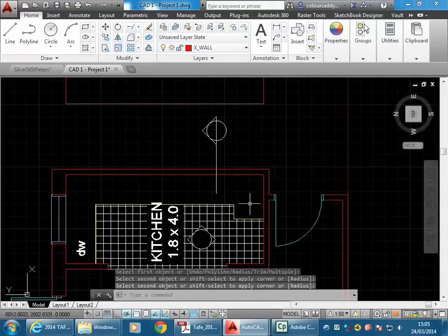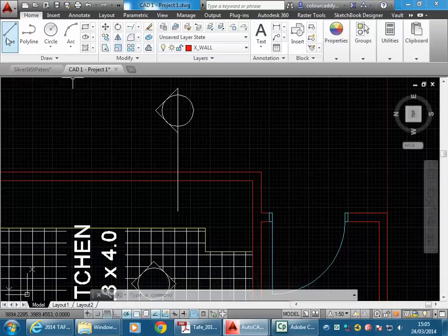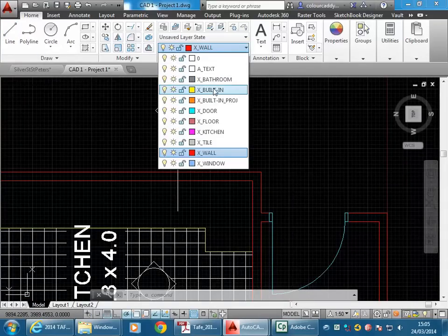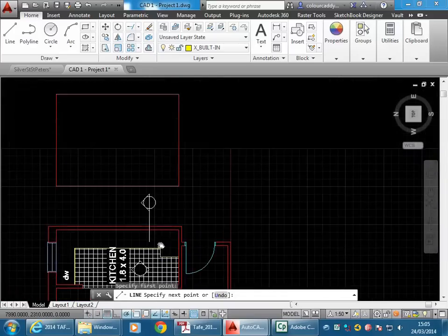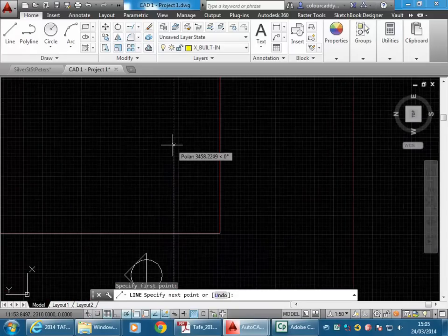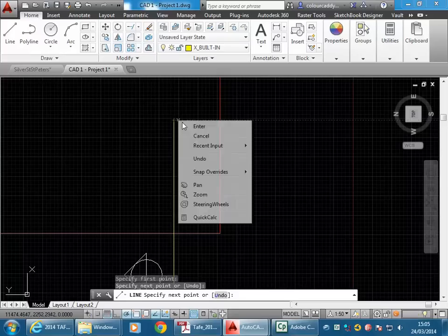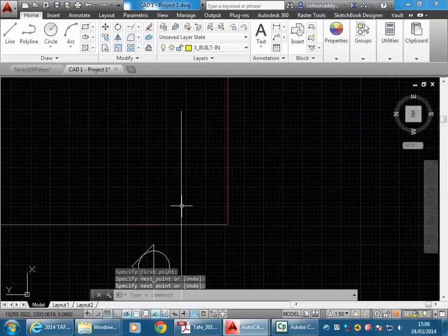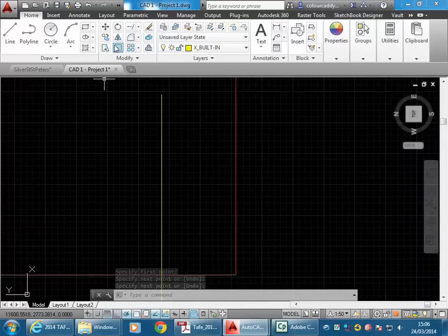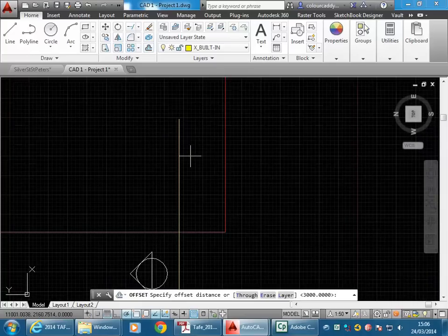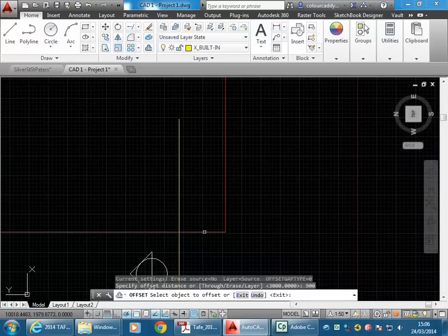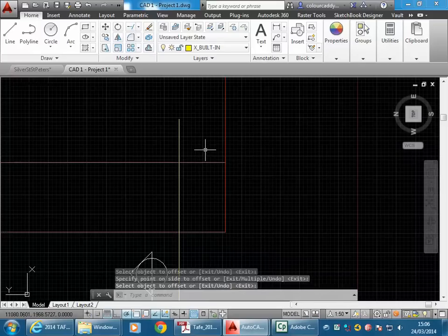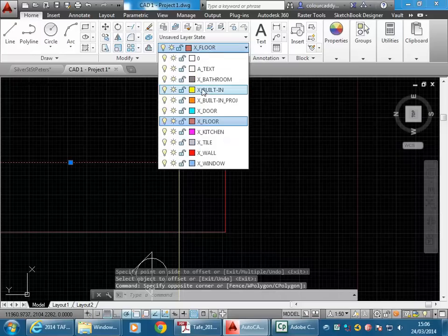And then you can project lines with, again, the layer from the plan. So drawing a line from the corner of the bench there. It'll be exactly the same as what's in the earlier video when I was projecting from the other elevation. So here, just come up, again, make sure it's a straight line, so I can then offset the floor, your bench height, 900 mil. From the floor line, come up, put that line straight onto the built-in layer,